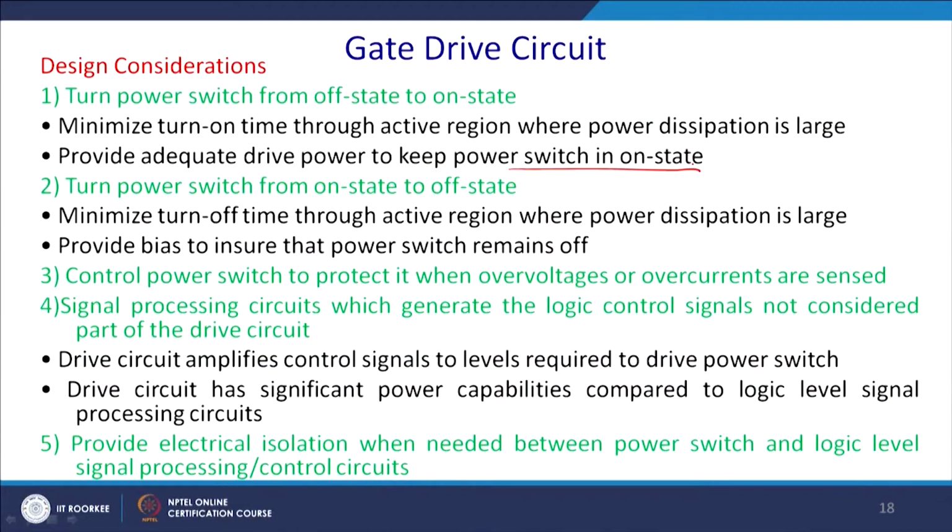Minimize the turn-on time through the active region, where power dissipation is large, and provide adequate driver power to keep the switch in the on state, in the case of MOSFETs and other devices. Turn the power switch from on state to off state, minimizing the turn-off time through the active region where power dissipation is large. Provide bias to ensure that